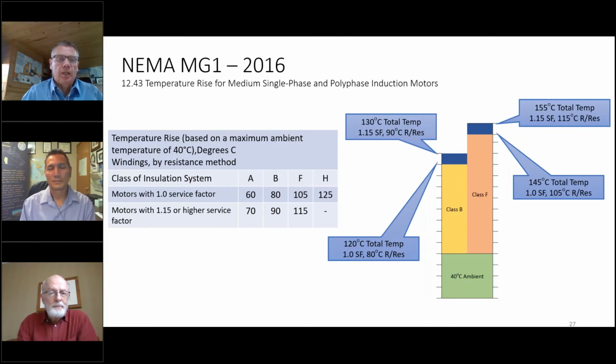But typically, if you see a motor that's nameplated for VFD use, there may be some derating for temperature rise because they're going to shoot maybe 10% additional heating. But it's well accounted for, and as long as the supplier of the motor knows it's going to be on a VFD, they can take that into consideration.